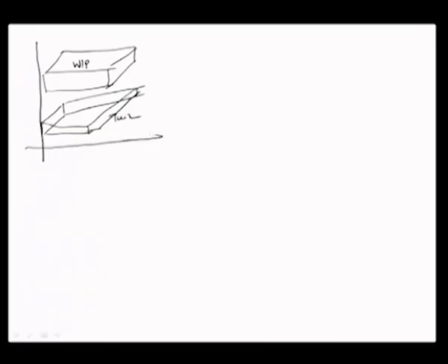So what we really modeled is that we assumed that there is a workpiece as indicated here, and then there is a tool surface indicated below, and this workpiece is moved slowly towards the tool in the minus y direction. This being the y axis, this is the minus y direction. So the workpiece is moved like this. And then we assume that there is a movement rate or feed of this workpiece towards the tool, assumed to be f.